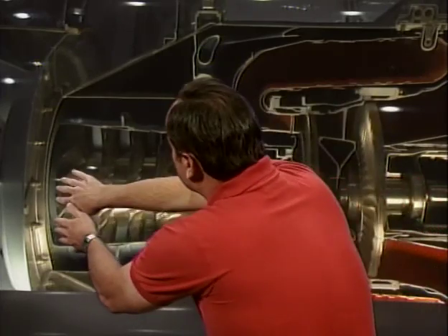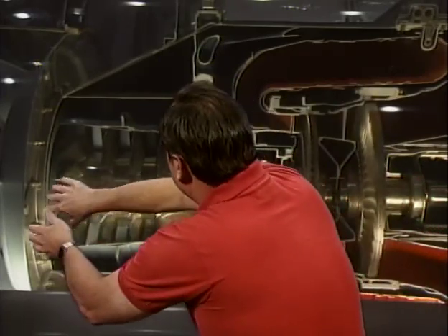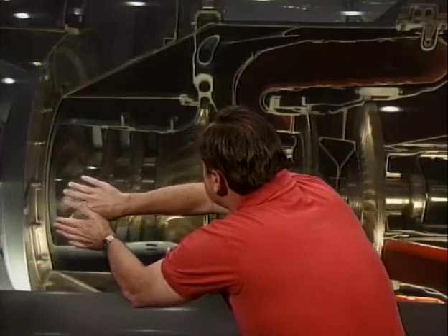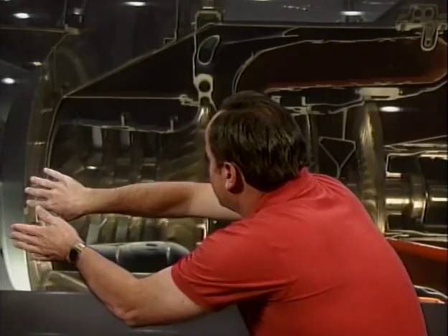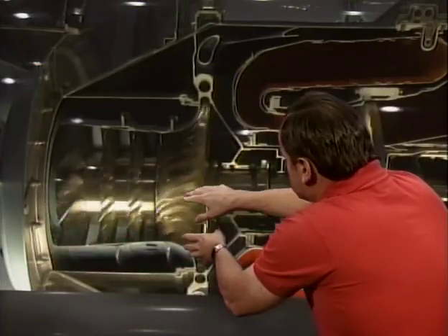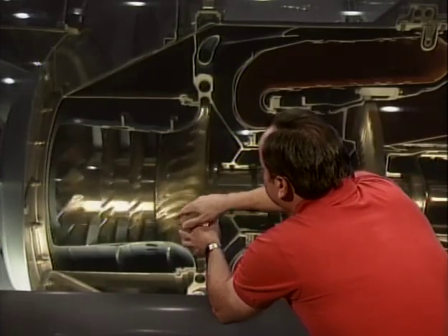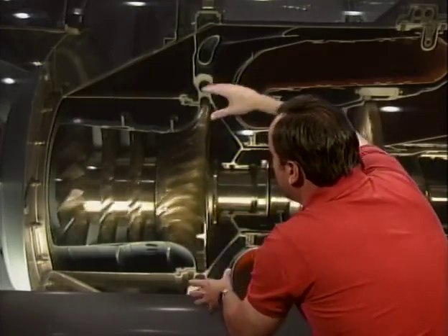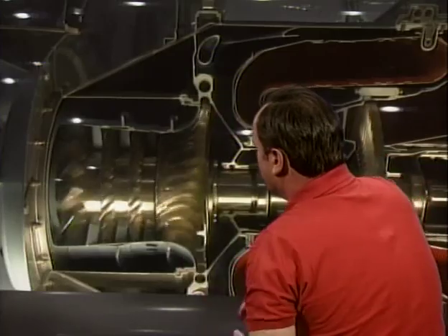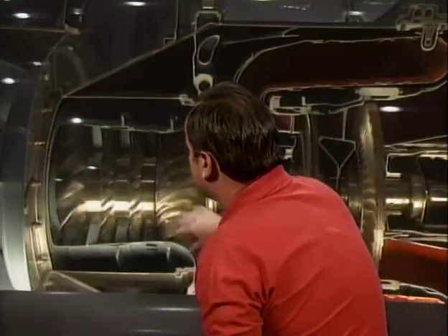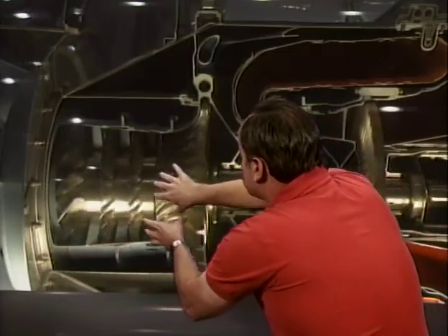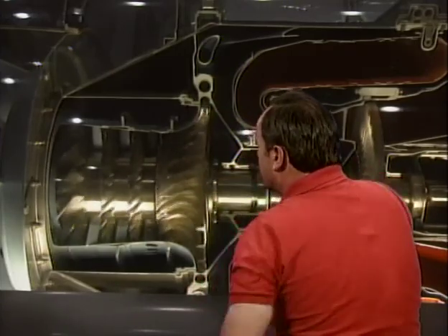Here's an axial compressor. This section is the axial part that moves the air along the shaft, or the axle, of the engine right straight back. And here's the centrifugal compressor that shoves the air outside, slings it to the outside of the engine, thereby increasing the pressure of the air. So these are the two types of compressor blades. They do increase the air pressure in the engine before the air enters the burner can.